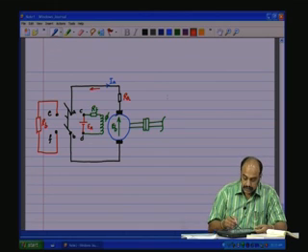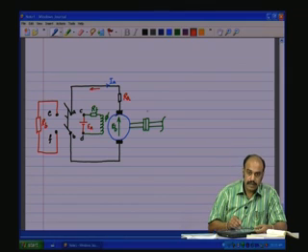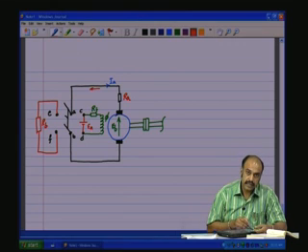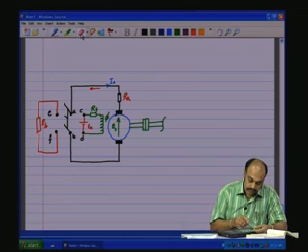So, therefore, the energy stored in the inertia, instead of being dissipated in the mechanical friction here, is going to be dissipated as electrical heat in the braking resistor RB shown here, due to the armature current now flowing through the resistor.